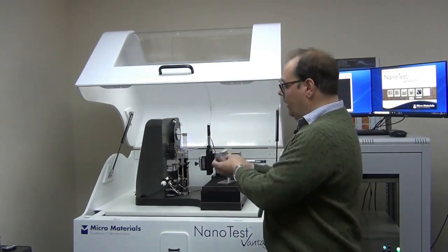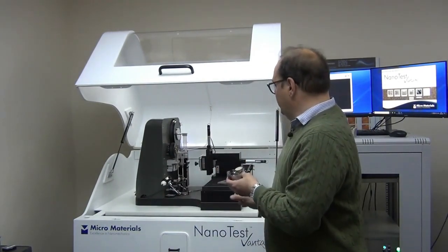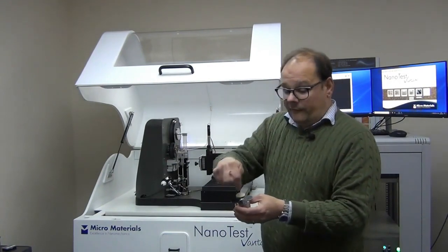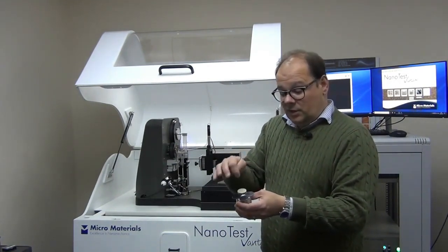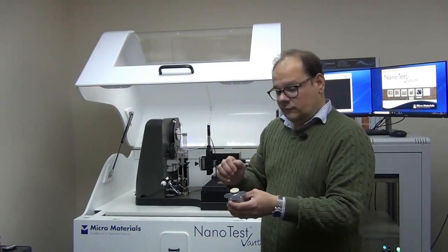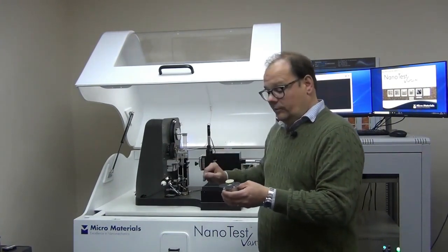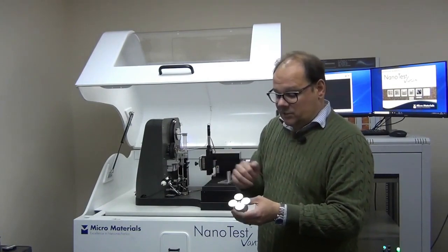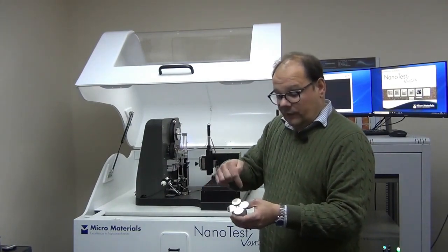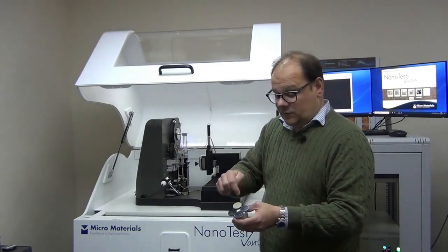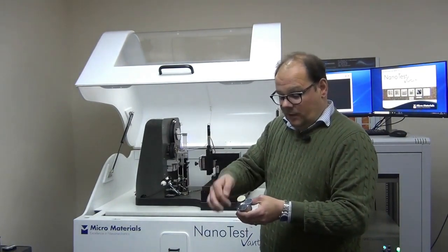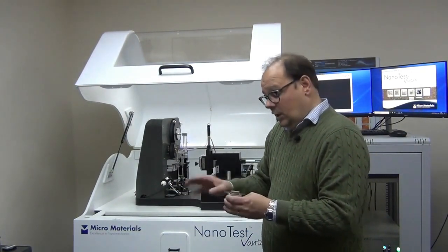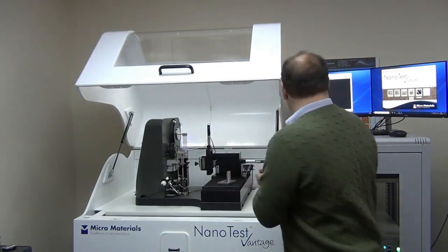We can mount all of those samples simultaneously on the instrument, reference the desired test start point on each of the samples using the optical microscope, define the experiments, and then the system will automatically run the tests on those samples one after the other. Perform tests on the first one, then move to the next one, then on to the third one, etc. With no user intervention necessary.